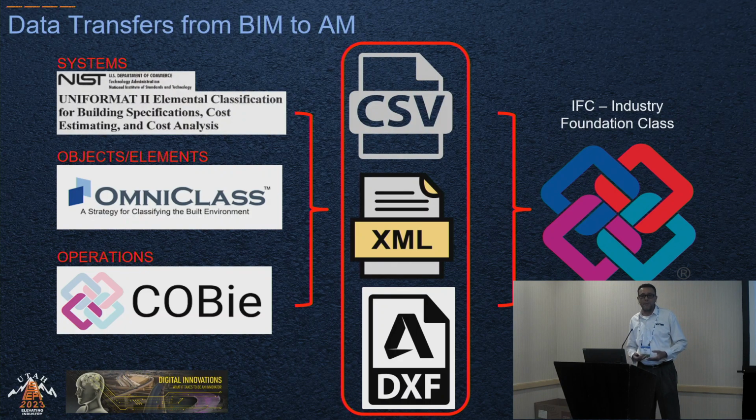But if you call for a model, we could give you a 3D DGN, we can give you a 3D DWG, we could give you a Revit model. Not a problem. The preference is to give the IFC because the IFC contains parameters and information that cannot be altered or changed. So there's a chain of custody there. Who designed it? When was it designed? When was it implemented? When was it put in place? When was the system organized? But you can build on that.